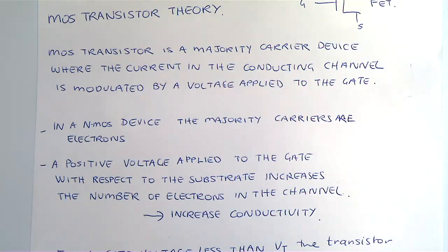And the reason I was mentioning this, but then I felt like, oh yeah, the effective mobility of electrons is always higher than holes, because the effective mass of the holes is larger than the electrons. But then I was like, oh, that's a bit of a circular argument, right? Because what does a hole mean? Because you're not actually transferring protons. The protons are actually stuck in the lattice, right? So what you're doing is you're moving areas of depletion.